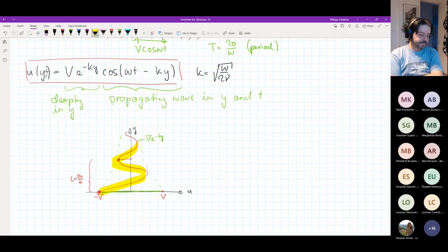Second possibility was smoothing of the velocity profile. Well, of course, that happens to some extent, but in this case, it's actually not so important because we only excite the flow with one wave number. So that means there's actually not much smoothing that needs to go on. It would be different if the waveform of the movement had higher frequency in it, so it would stop and start and have shocks and so on. Then you would see this smoothing of the velocity profile. In this case, this is actually not the relevant part.